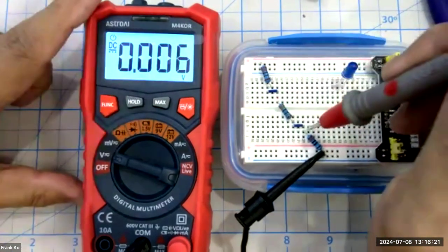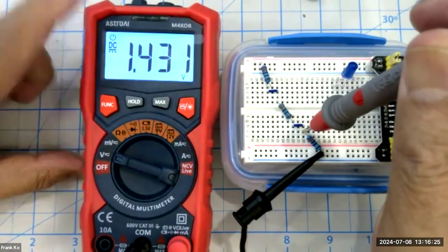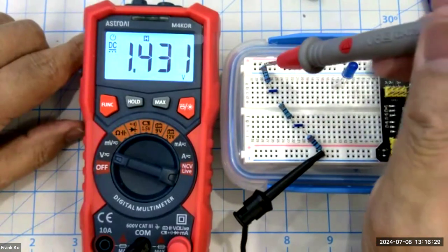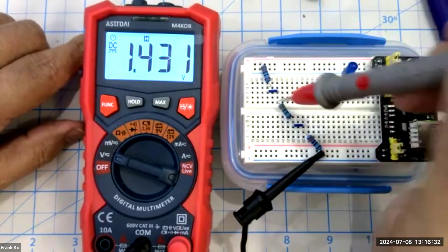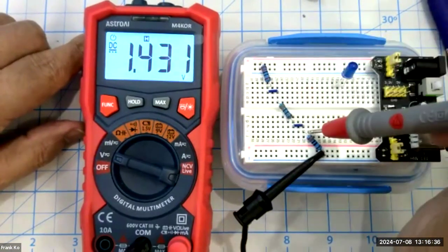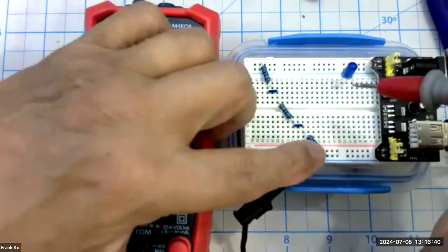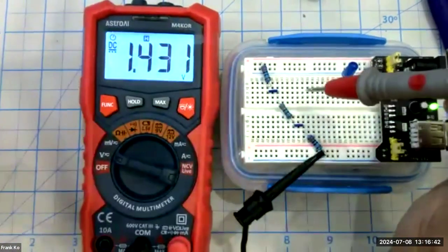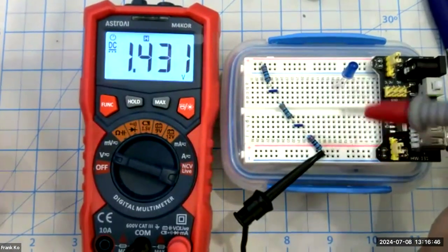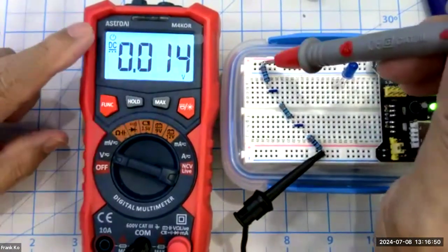All right, so let's go ahead and do the last one here. We expect 1.43, and we have 1.43. Okay, so with one probe, test point 2, test point 3, you can see how fast and easy this is in the field, not having to use both hands to hold probes. You simply lock the black probe onto ground somehow. You could do this with an alligator clip, or you could do this with a mini hook. Once that's locked on ground, then you just simply go to the individual test points.